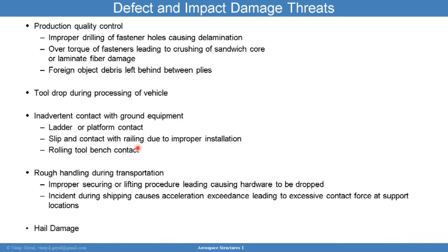The catering truck, trying to deliver food to the aircraft, basically hit it at low speeds, but at high energy, and did cause some damage to the stiffening elements of the composite system. That's an example of something that may not be visually seen until there is some rattling going on during flight.